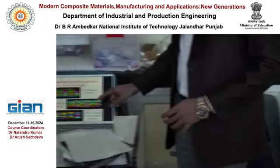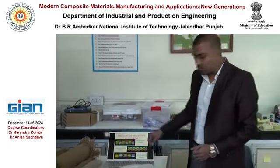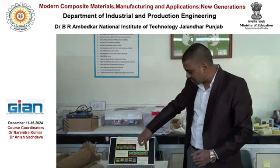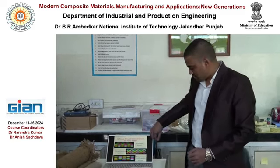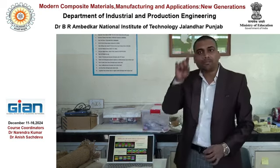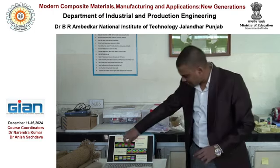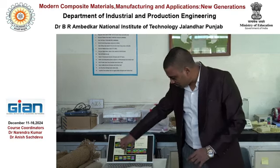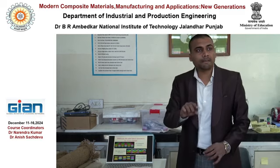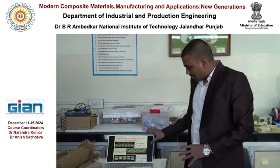In case of angle interlock structure, the binder moves through the structure. It goes through the structure from one side of the fabric to the other side of the fabric, and again on the surface, from the surface to the back, again to the surface, and it moves through the thickness of the fabric at certain angle. If you look at the layer to layer interlock, here different layers are interlocked with the help of binder.